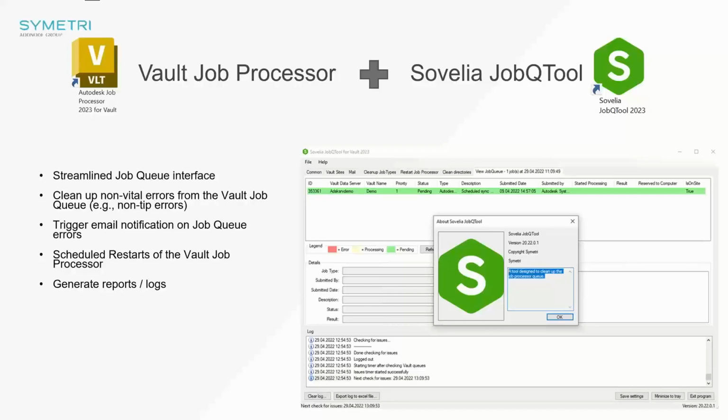Other useful functions: schedule restarts of the Vault job processor. On rare occasion, the job processor can get stuck and you can end up bottlenecking jobs into the Vault job processor while we're waiting for someone to realize that the job processor has gotten stuck. You're essentially building up a backlog of jobs. Or let's say a job in the job processor freezes, we can set up scheduled restarts that will prevent those kinds of situations from occurring. Essentially, you could have it so that the job processor restarts at the end of the day every evening, and if jobs were ever stuck for any reason, it would just move on to the next job, and that particular job would just return an error.